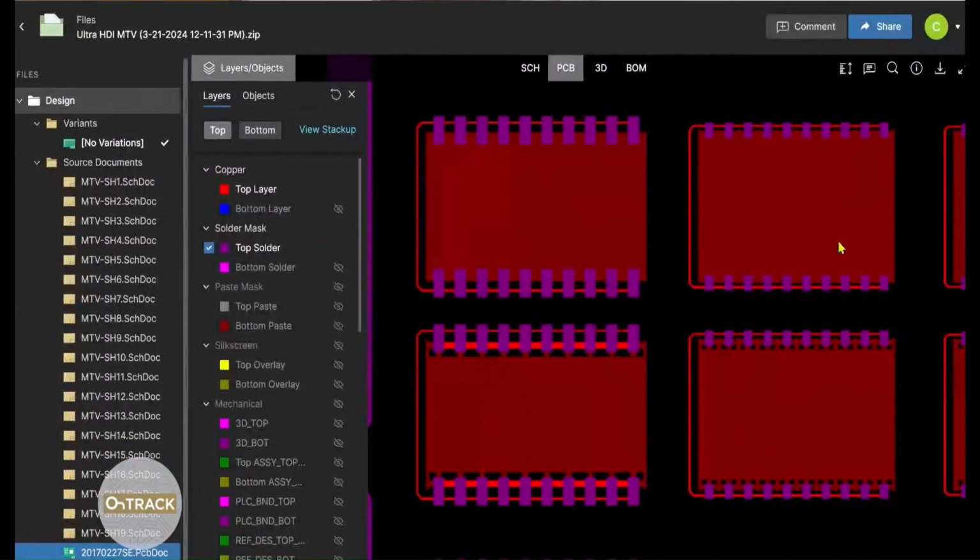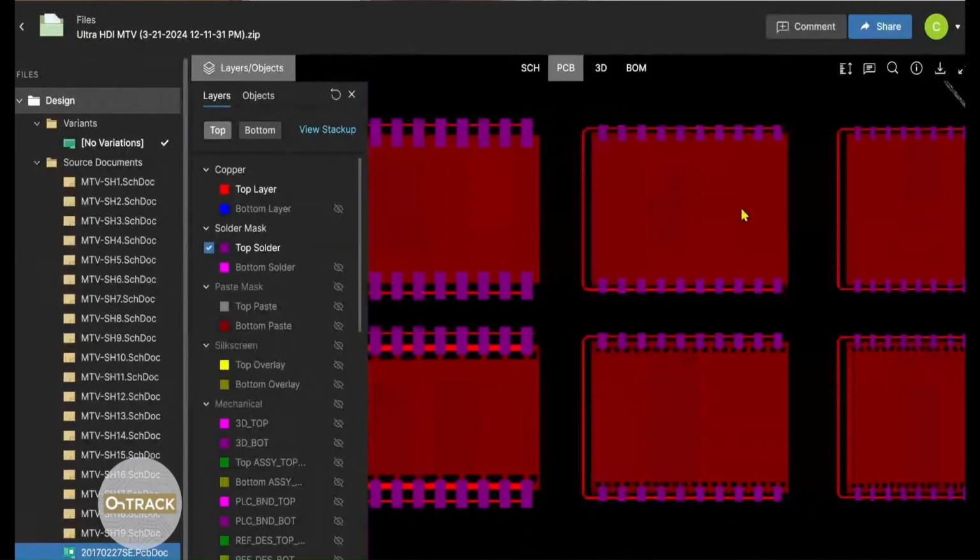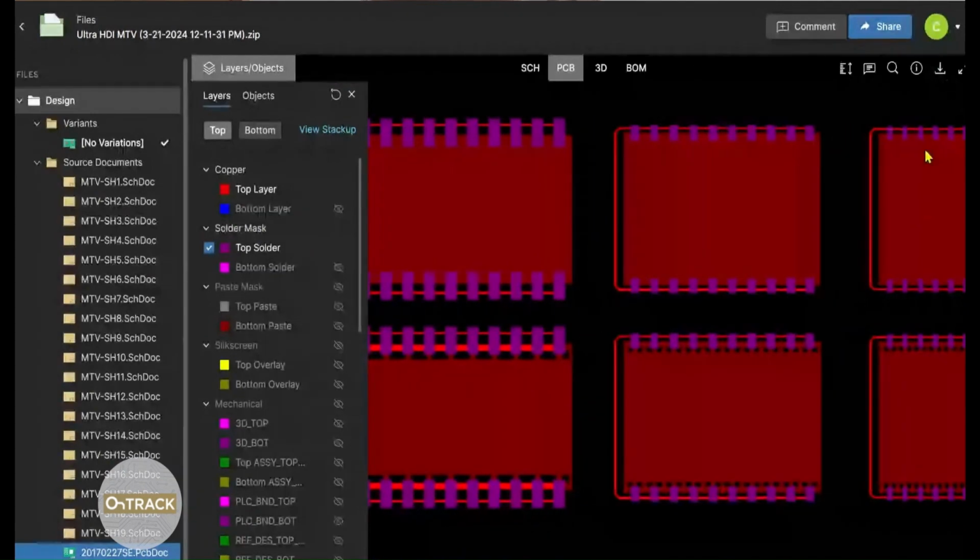We built these tombstone alleys for our 0201 caps, our 01005 caps, and our 0804 caps. Caps are a lot more likely to tombstone than resistors because they have 5-sided terminations. And the mechanism by which tombstoning occurs is the melted solder wets to one end, and the surface tension just pulls it right up. So whichever side melts first is the base of the tombstone. Yeah. Resistors don't tombstone as much because they only have 3 sides of metallization. So there's not as much metallization for the solder paste to grab.